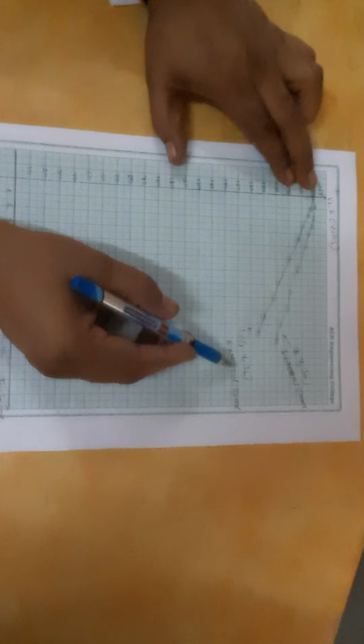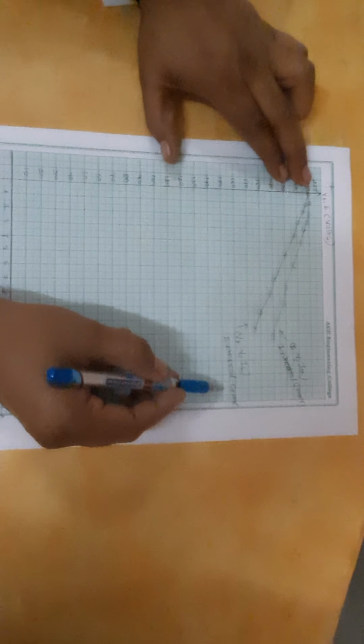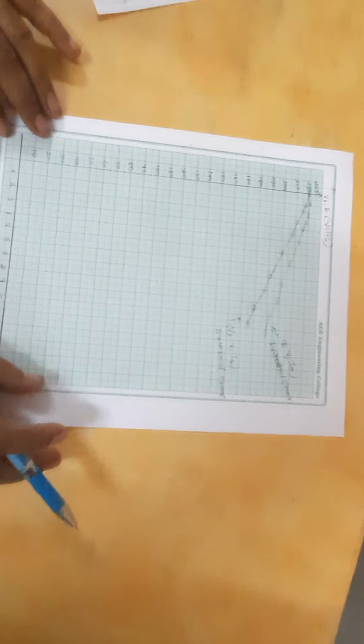Next, another one with respect to IL, draw this graph. With respect to IA, again put the values. Now join all the points here. You will get VT versus IL, and this is known as external characteristics, and this one is known as internal characteristics, E versus IA. Once this is over, then your experiment is over. Okay, thank you.